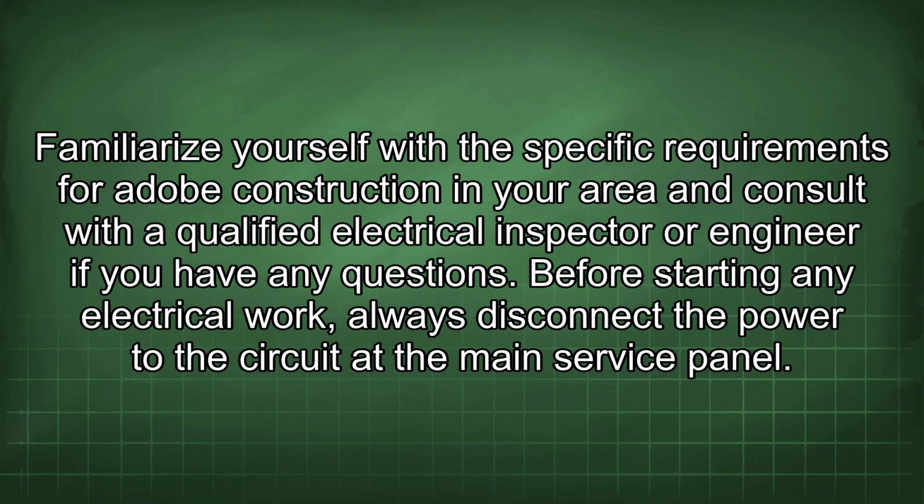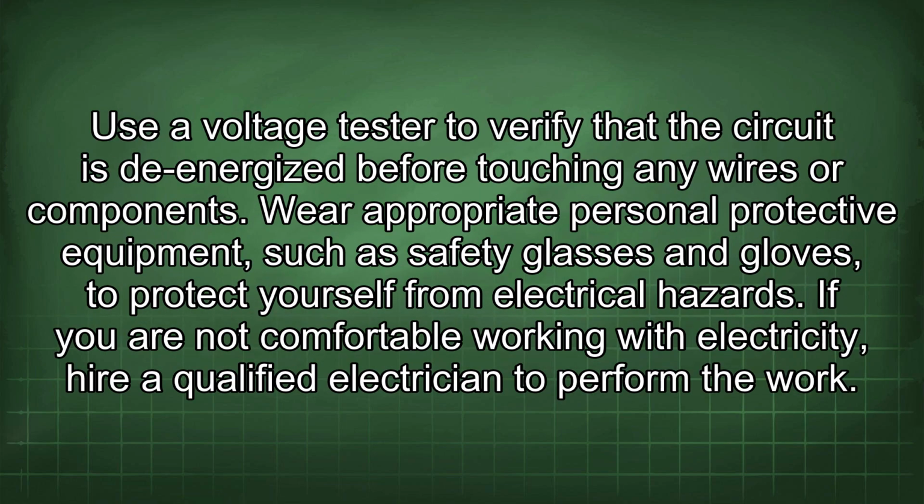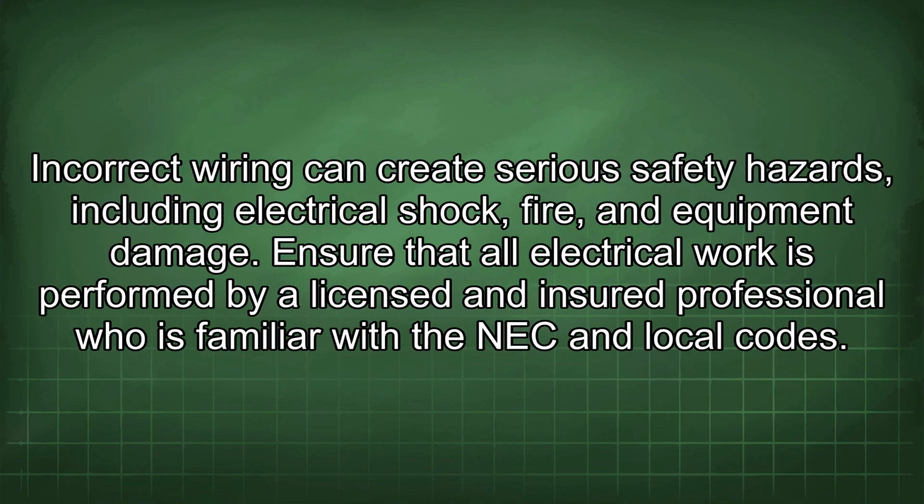Before starting any electrical work, always disconnect the power to the circuit at the main service panel. Use a voltage tester to verify that the circuit is de-energized before touching any wires or components. Wear appropriate personal protective equipment such as safety glasses and gloves to protect yourself from electrical hazards. If you are not comfortable working with electricity, hire a qualified electrician to perform the work. Incorrect wiring can create serious safety hazards, including electrical shock, fire, and equipment damage.